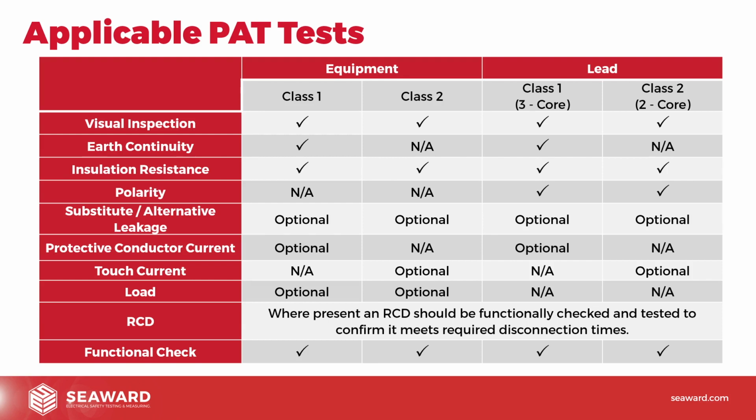We don't do tests for the fun of it, we do tests to actually determine what the safety status of the equipment is. So if a test isn't going to tell us anything about the safety status of the equipment, there's no real point us carrying that test out. So from that side of things, we need to do just the test that we need to get the full picture. But quite often, people make the mistake of missing out tests that could have potentially detected a fault because they're just not aware they're available or they just don't think it's necessary.